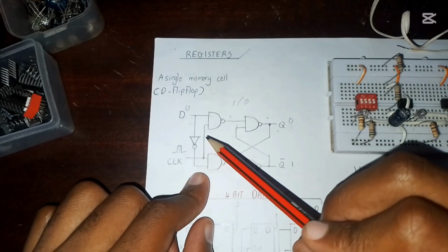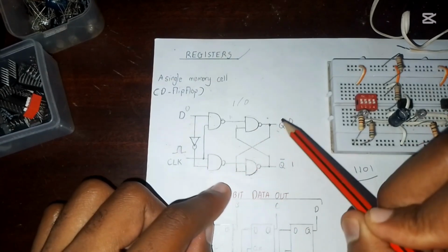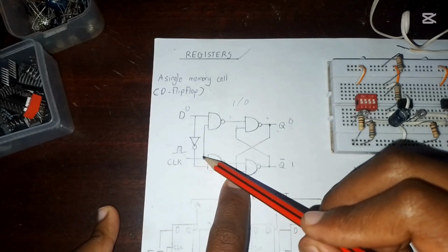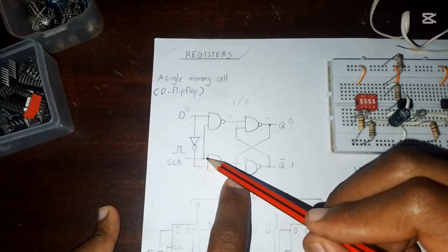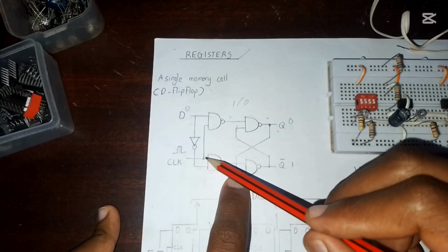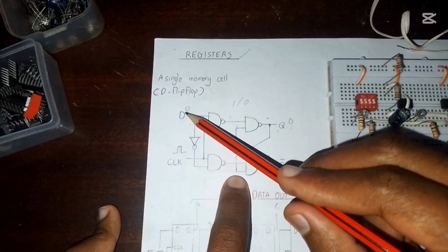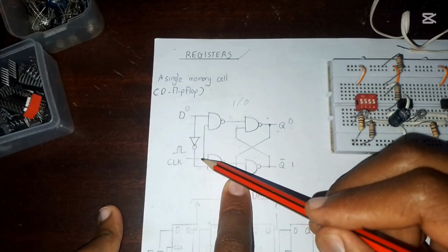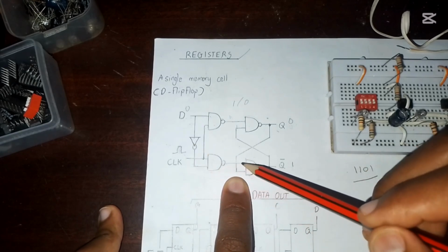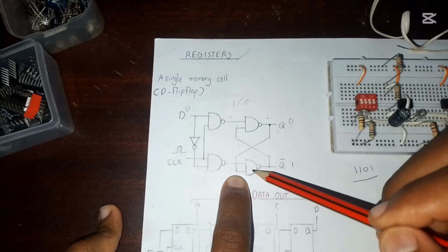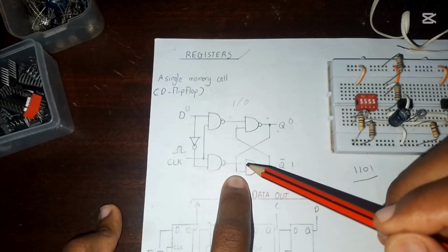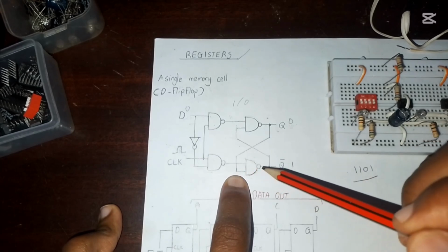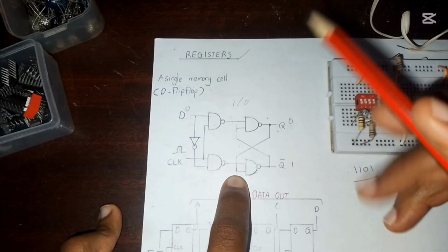Okay, let's check on this lower part of the circuit. So this 0 enters here. This clock, remember we said that it's 1. So 1, it gives a 1 in this input. Then the data, remember we said that it's 0. So when it passes through an inverter, it's going to be 1. So 1 1, it's going to give you a 0. So this is a 0 and this is a 0. We said it's only going to give you a 0 output when both inputs are 1. So because these inputs are 0, both of them are going to give you a 1 output. So nothing really changes in our circuit.